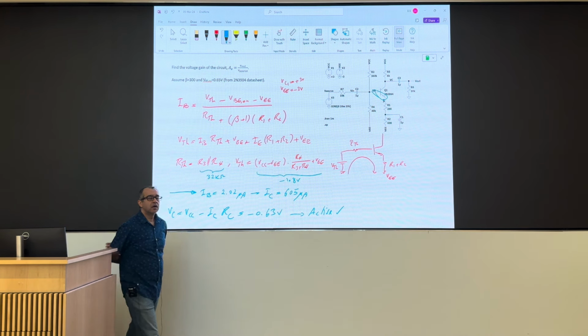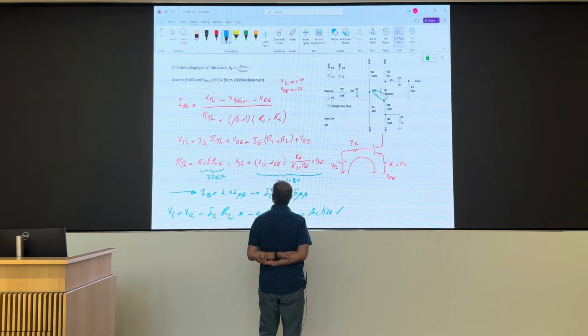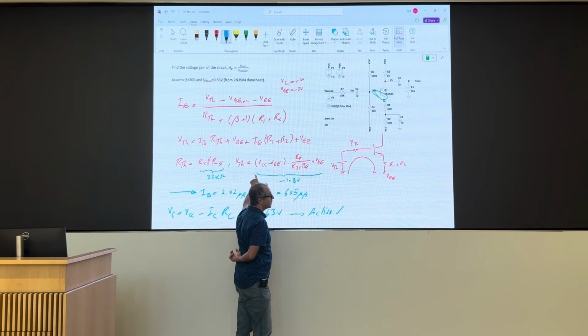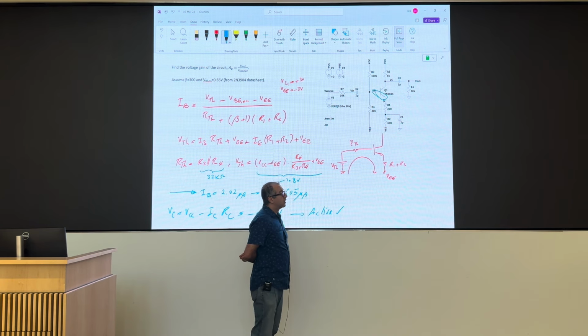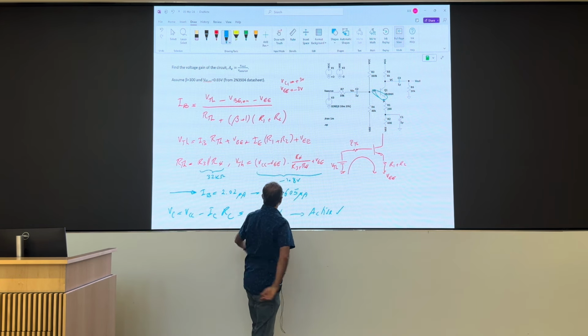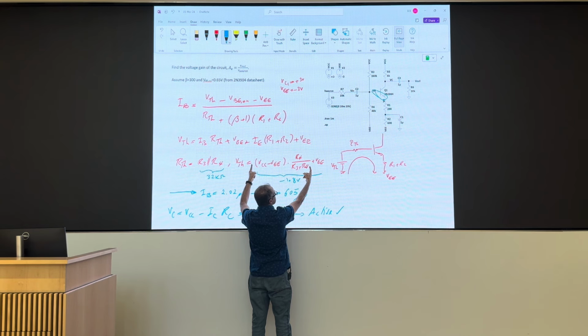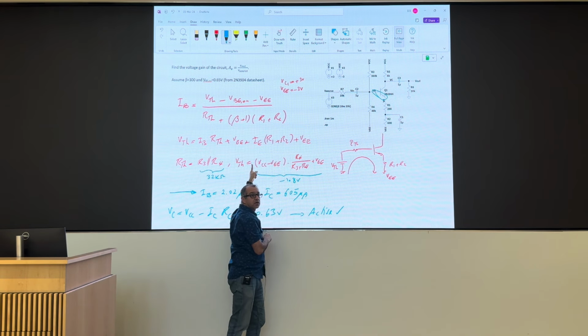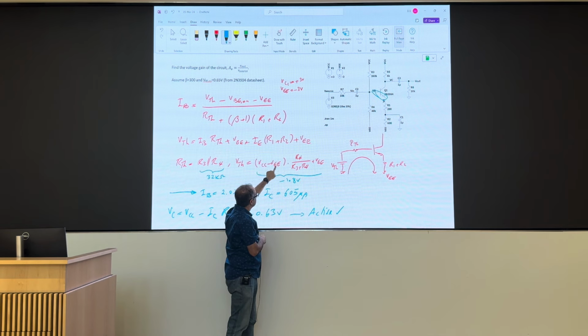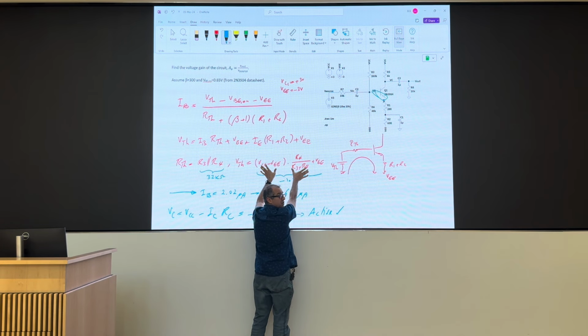Sorry, just a question on the VTH, the one that equates to 1.8 volts. That formula, where does it come from again? This is the voltage drop across R4, right? Because you have 3 at the top minus 3 at the bottom, so that's 6 volts, times the division ratio, R4 over R3 plus R4.